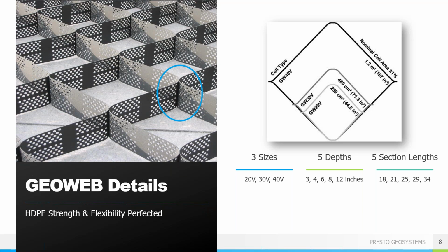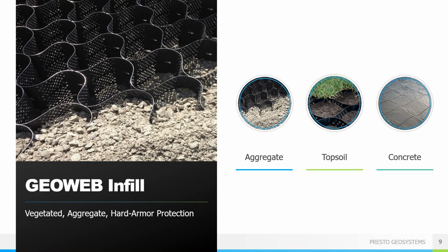The ultrasonically welded seam, that's where all the connecting points are, is really important to the function of a GeoCell. The stronger the seam, the better the performance. And that's period. The material is constructed out of 100% virgin HDPE, which provides the strongest wall strength that you can get, but also maintains semi-rigid properties, so somewhat flexible. Too stiff of a cell wall really does lead to overstressing of the seams and a potential for actual cell rupture.